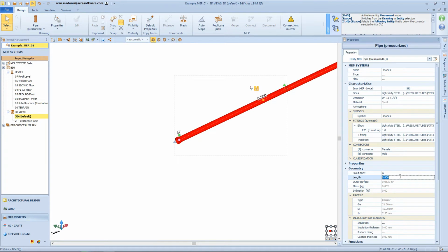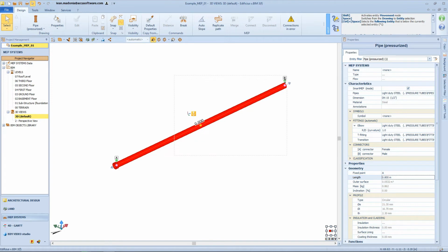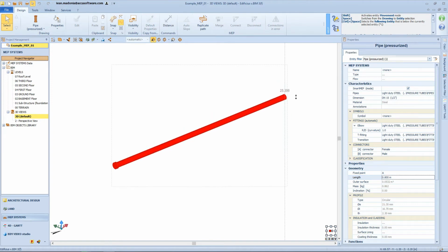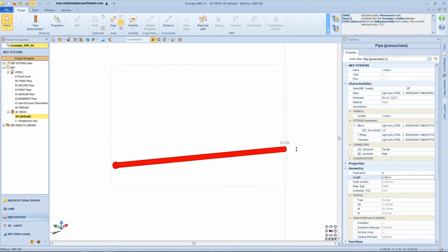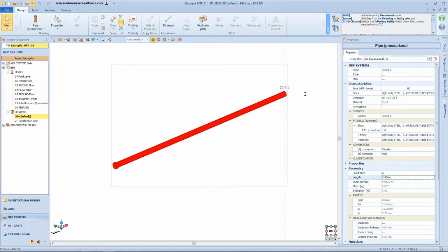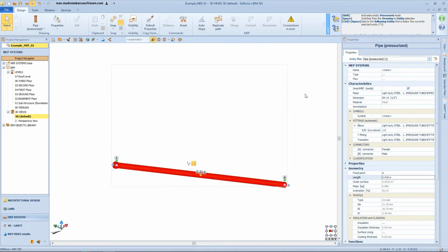The green arrow, on the other hand, allows you to change the height of the selected attachment, leaving that of the opposite attachment fixed. If you click on the green arrow with the mouse, the pointer takes the form of a double vertical arrow and is positioned in the center of gravity of the corresponding attachment. The displacement of the selected attachment is constrained along its vertical, and you can reshape the pipe by setting a new value for the height referred to the zero of the building. Furthermore, for this property you can choose the elevation value on screen or type it from the keyboard. As a result, the pipeline length is automatically adapted and changed.